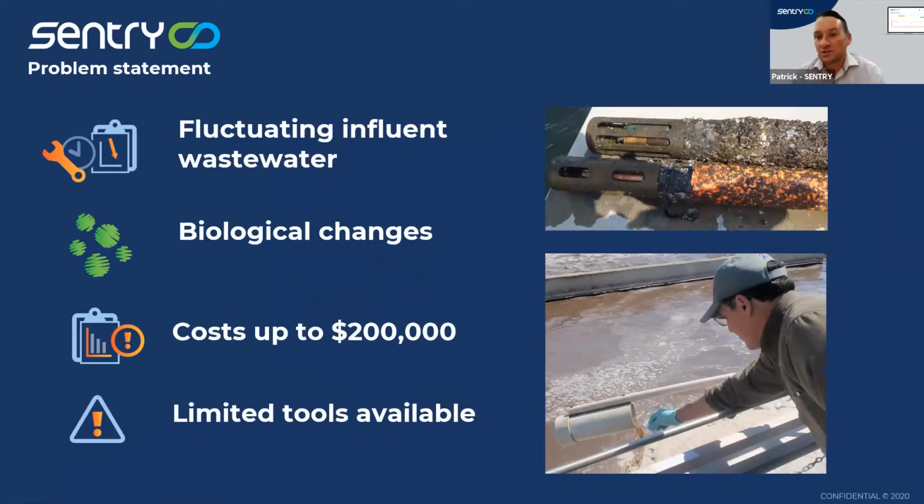Wastewater treatment, biological treatment of wastewater. It is a job that I think has been undervalued. We understand that wastewater conditions coming into a wastewater treatment plant are always changing. So whether it's diurnal trends of organic load coming into a plant, whether it's industry discharging big slugs of BOD or COD, not always at the same time, whether it's industry disposing and discharging acutely toxic materials into wastewater collection systems, all of this wastewater change comes down the pipe and gets to a biological wastewater treatment plant.